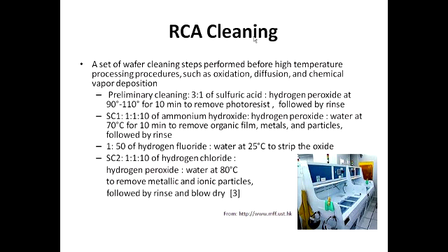Here is the RCA cleaning, what we did in class. Preliminary cleaning is to remove photoresist using sulfuric acid.